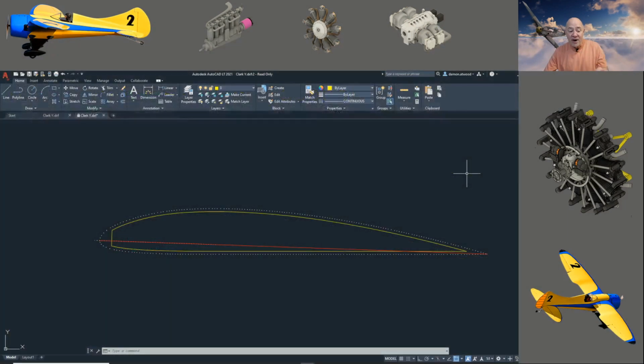But when you put it on the aircraft, this is the way the incidence would be set up, about 2 degrees positive incidence with the flat bottom of the wing on the fuselage. This is used in Cubs. I've actually stuck this on warbirds, and it works great.